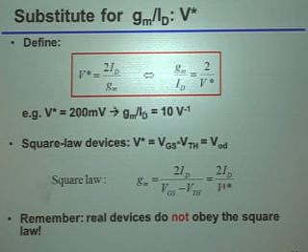So the only reason I chose to define things this way was, again, because I'm trying to make an analogy between VGS minus VT, or that overdrive voltage, and this V star. But notice the really big difference is that because this is by definition, I can always actually measure V star. Whereas VGS minus VT, I have no way of actually measuring, right? I don't actually know what that is because, again, I can't actually get at the threshold voltage, okay?